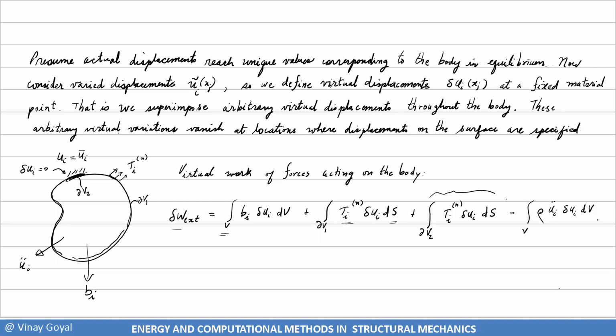And I'll demonstrate for you that those are going to be the Euler-Lagrange equations, which is very powerful. Have you seen me use Newton's law here? No, I have not. So that's very powerful. I'm going to be able to derive the equilibrium equations without using Newton's law, which is the summation of forces equals ma, which I covered in one of the earlier lectures.